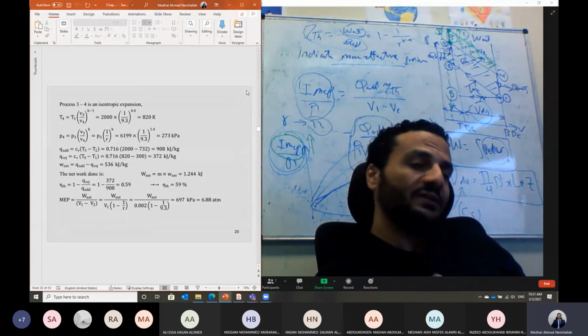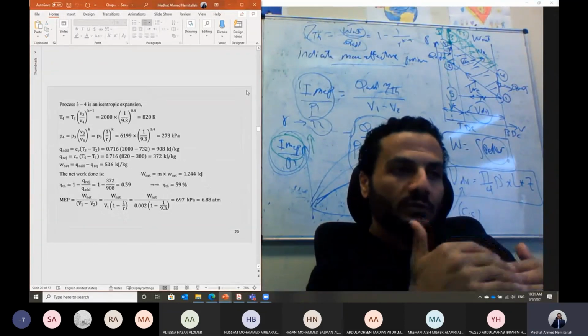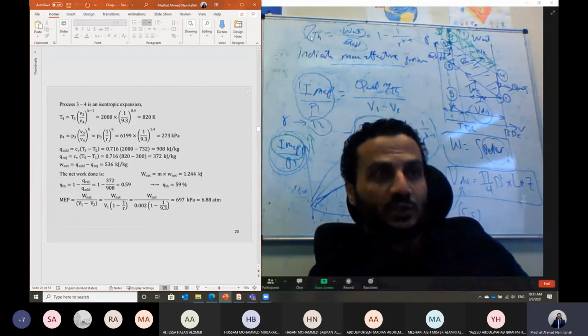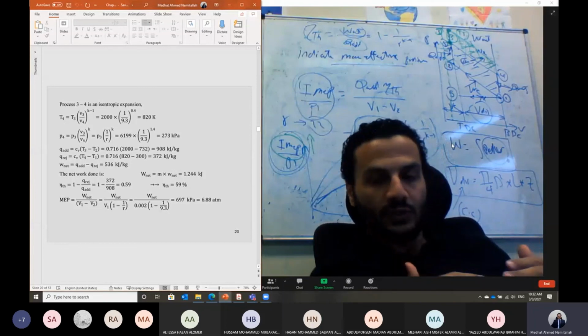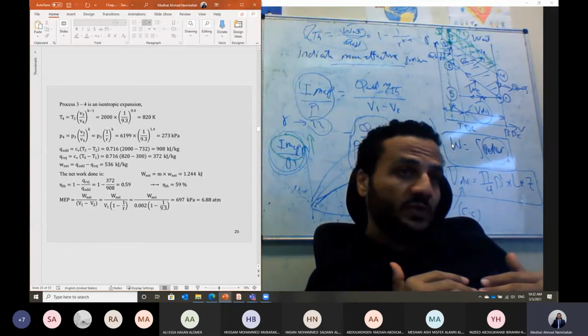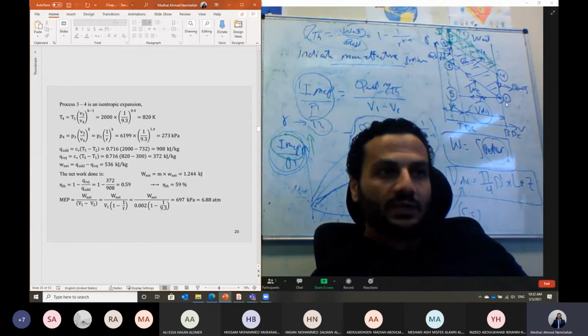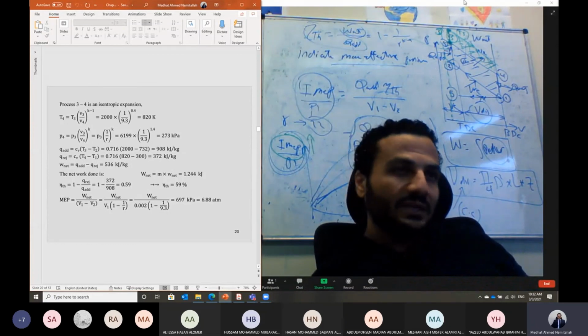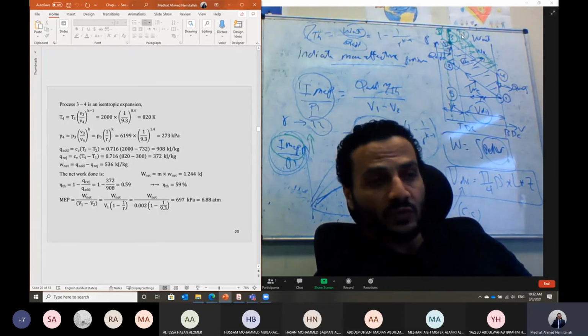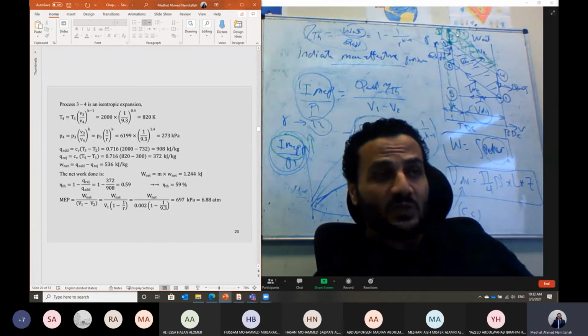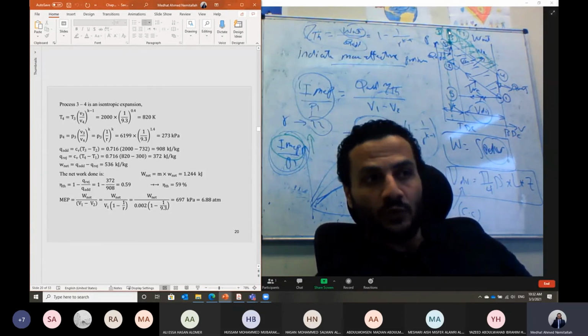So this is an ideal way to follow what is going on inside a gasoline engine, starting from the beginning of the compression stroke until the end of the expansion, and also the exhaust stroke. But this is based on the standard Otto cycle, which is a reversible cycle. It can give a theoretical indication about the engine performance, a rough analysis or a very close value to the actual value, especially for the maximum temperature and maximum pressure inside the cycle, which is the state at point 3.